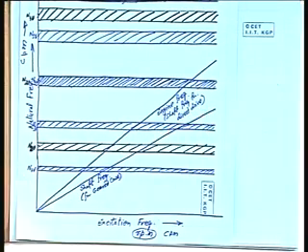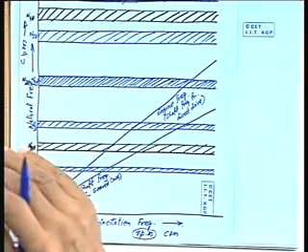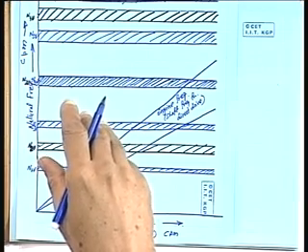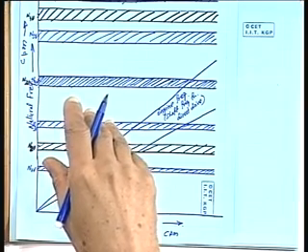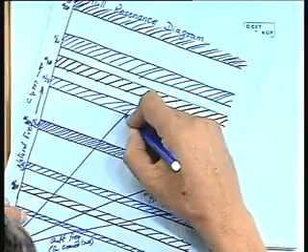Now, if you have a 3-bladed propeller, then the shaft frequency times the number of blades, 3 blades, will generate your blade excitation. Blade excitation is shaft RPM multiplied by the number of blades on the propeller. So, if you have 3 times, then it will be this.